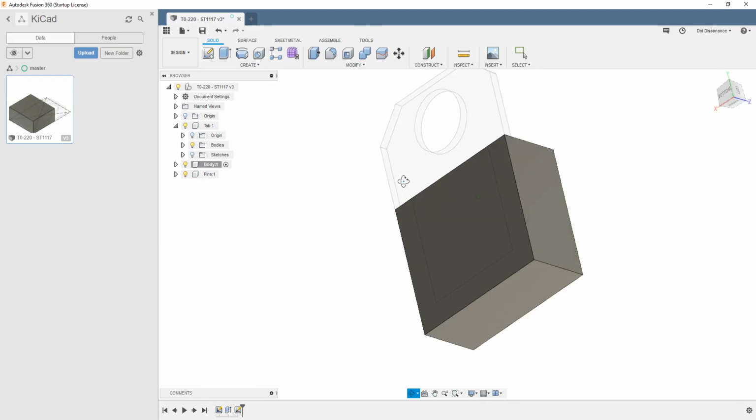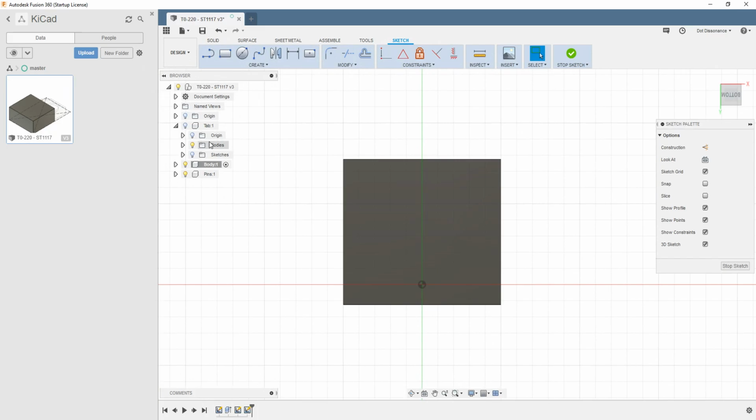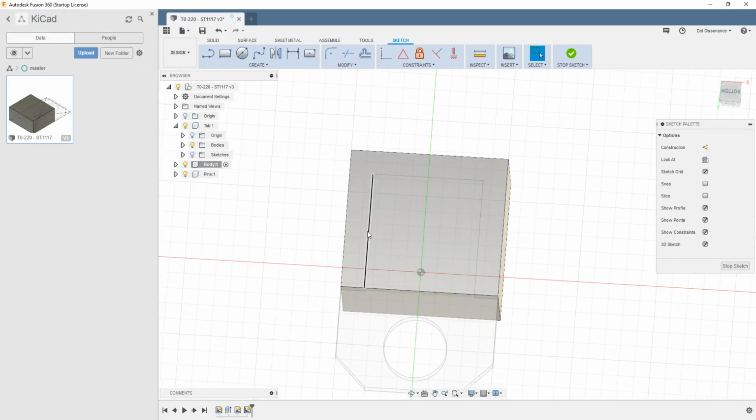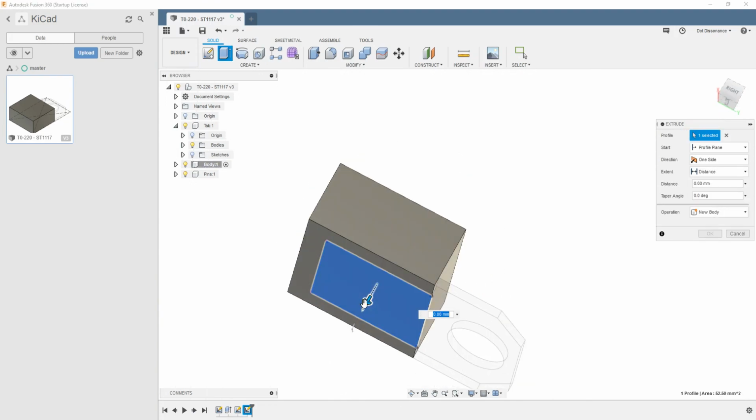All right, I'm going to roll this over onto the back side here. I'm going to hide the tab temporarily so I can pick this bottom face easy. I'll pick that, go into sketch on the bottom there, unhide tab, and catch just that edge there. And I'll project that forward, and I'm not going to make it a construction element. I'll just leave it there. And then we'll grab a line tool, go across there, and then we're going to extrude this up, extrude cut. But oh, hide tab.